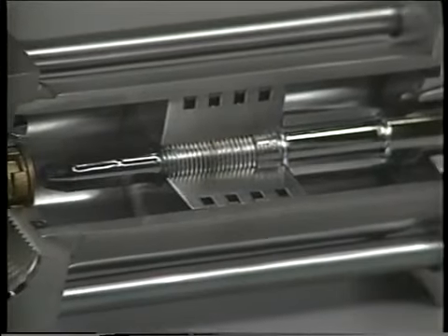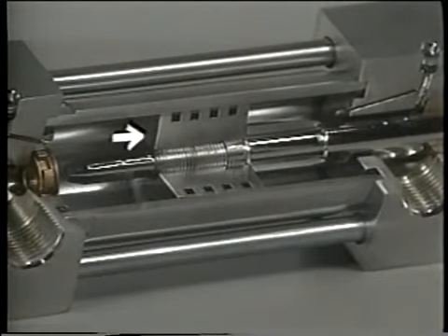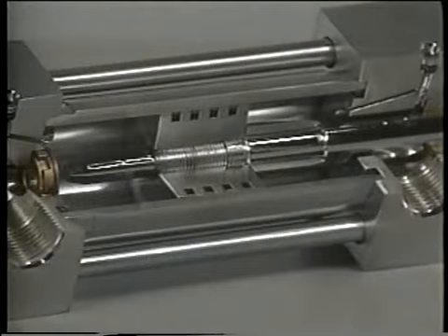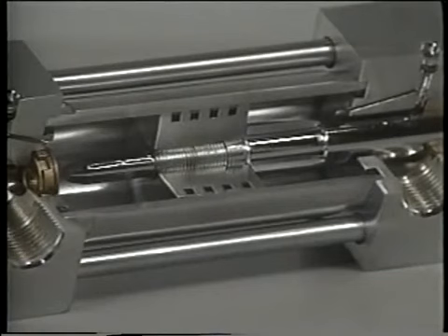In a cylinder, the area we apply the pressure to is the face of the piston. Frequently, though, we don't know the area of the piston face. Usually what we have is the piston's diameter, or the bore of the cylinder as it's called. That's the distance from side to side through the center of the bore. Finding the area is easy.